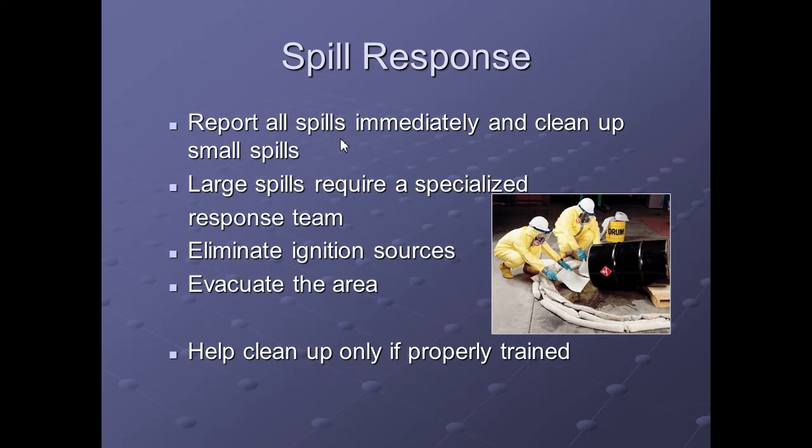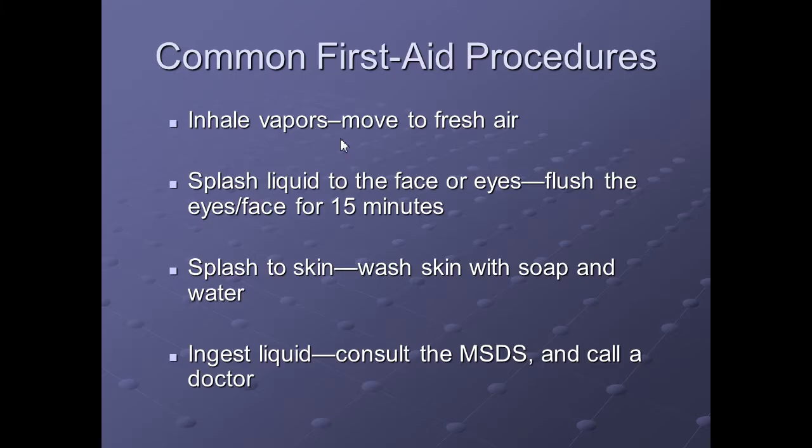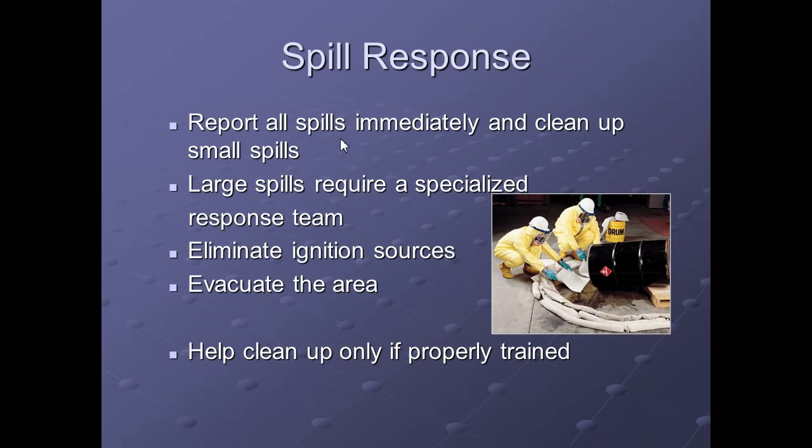So get out there and grab that SDS as quickly as you can. The best way of doing a spill control plan is to know what you're dealing with ahead of time. Do a job safety analysis before you even do your lab sample, so you know the hazards associated with this job. Here's what we're going to do if one of those steps breaks down and we have an exposure. This is how we're going to fix that exposure, and that's your spill control. If it's a big enough spill, you may need someone more qualified than yourself, and you'll have to call them in.